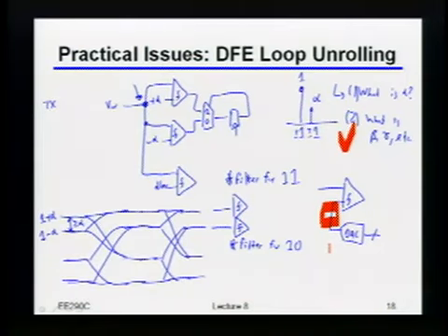So really the big difference here from everything we've been doing so far is that there's no real analog voltage level that you can filter the data to find what the right value for alpha is. Right? In all of the other things, we had basically these closed loop systems that would drive some error value to 0. And when we got that error value to be 0, we knew that we were at the right spot, independent of what the transfer curve of the DAC was. Here, there's no closed loop thing you can really do. All you can do is go from this point to this point, and then rely on the DAC being sufficiently linear. If it is, then life is good.